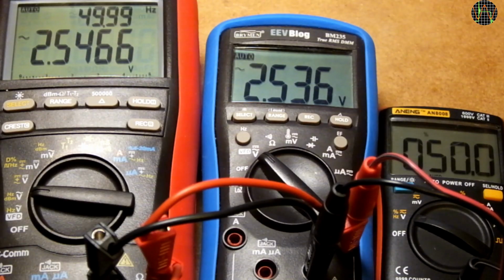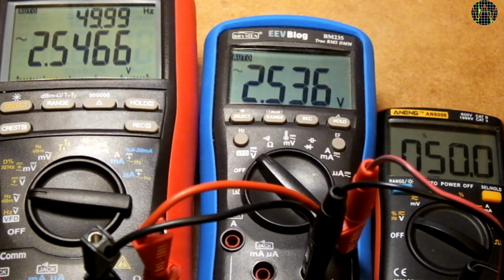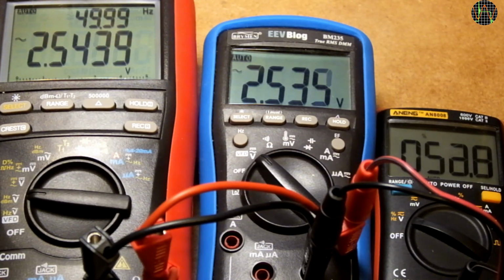Now I do the same test with two multimeters connected, both display AC volts through RMS. The small one on the right is instead showing the duty factor. At 50% the RMS values agree with each other and the scope value of about 2.5 volts. There's some noise on the signal due to the long cables, which cause a slightly higher value, but for this test it doesn't matter. At 60% the voltage has dropped already. At 70% both are reading about 2.33 volts. And at 80% we are down to 2.03 volts.